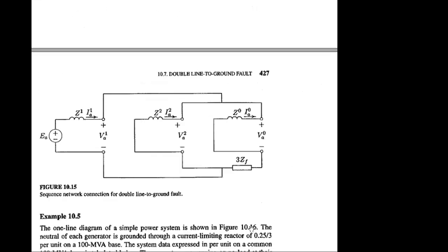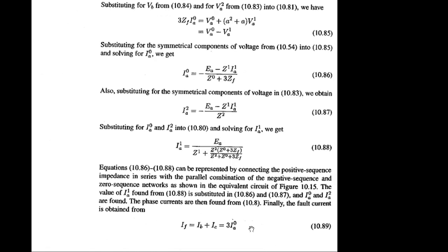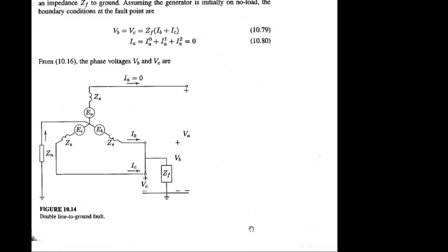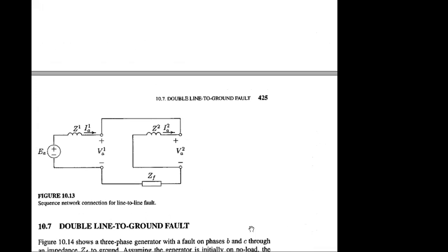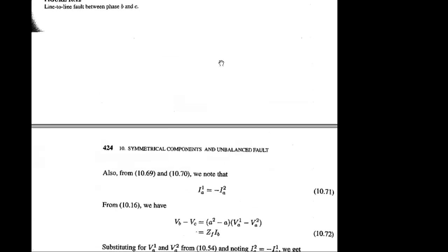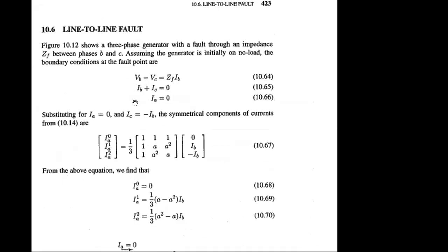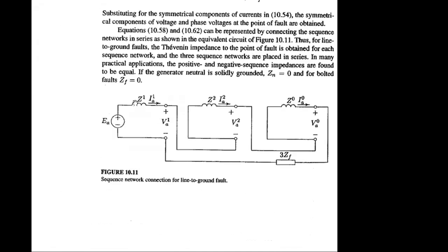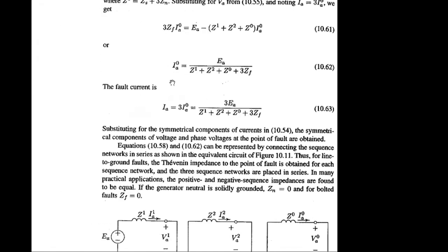If you recap the idea, what are the different fault scenarios? The expression looks like Z1, Z2, ZF, IA equation. It can be different for other scenarios, like the single line case, where the IA expression will have Z1, Z2, Z0 as well as ZF.